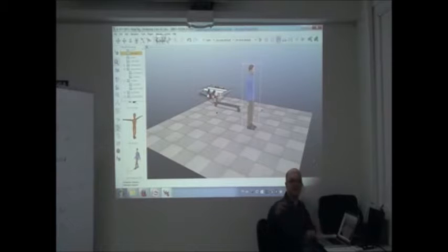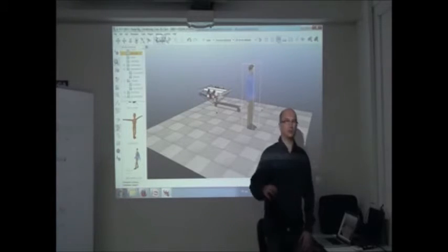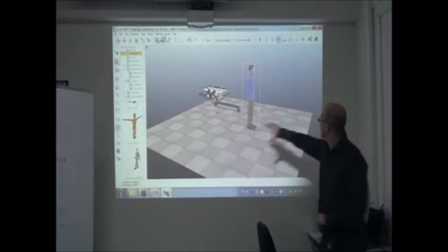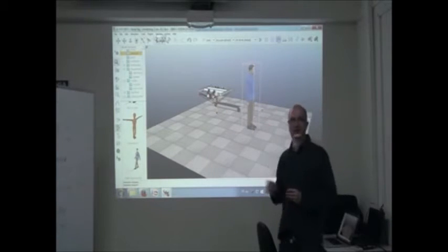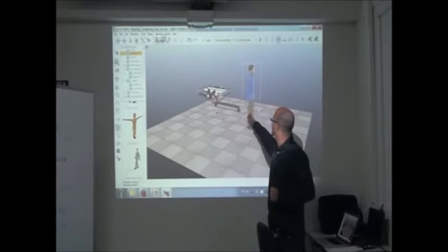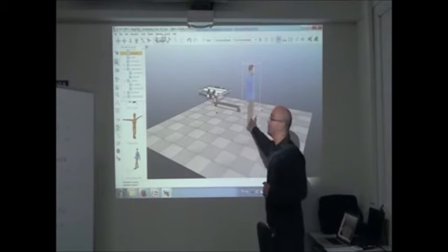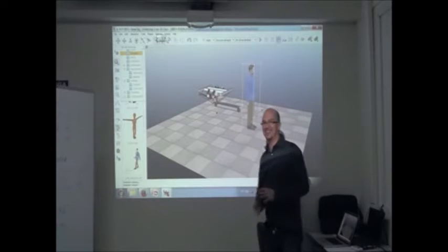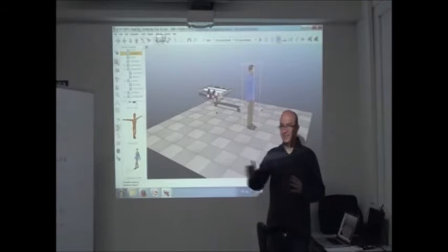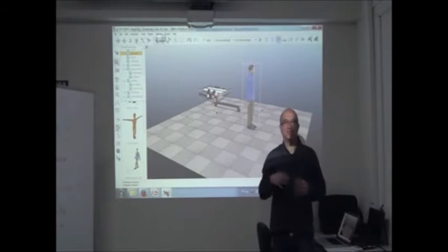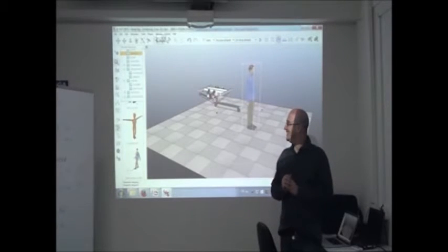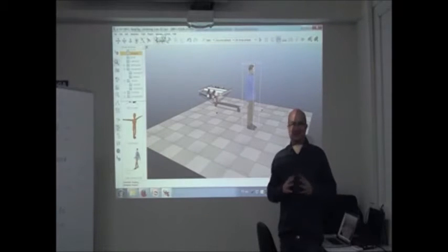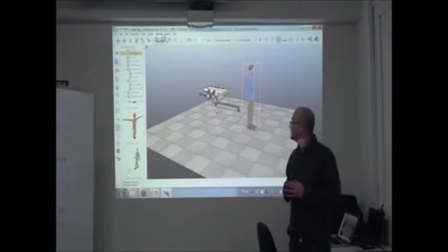So this might be interesting for you in order to test. You mount your manufacturing in VREP, and then you put some people. You can script the motion of some objects, like people objects. This guy is an object in the simulated world, and you can simulate a motion or a behavior that is not recommended in an industry or manufacturing plant, to test your safety systems or something like this.